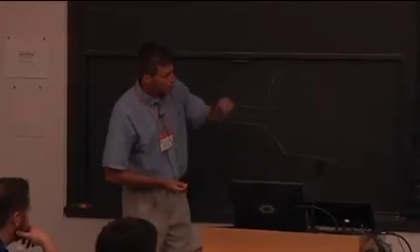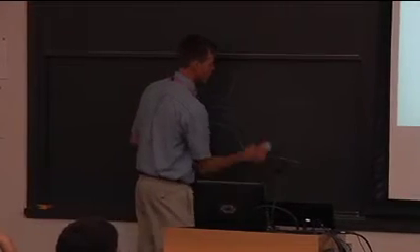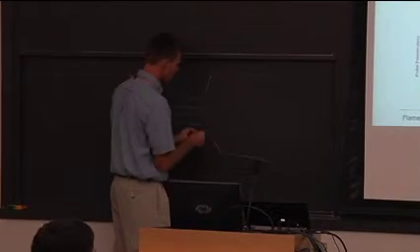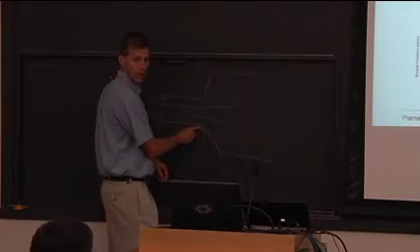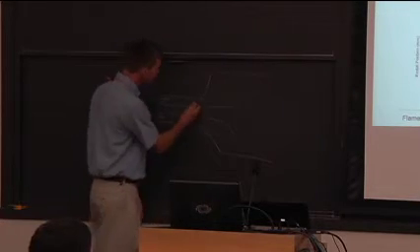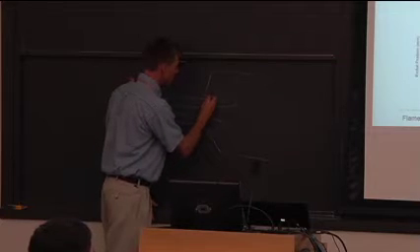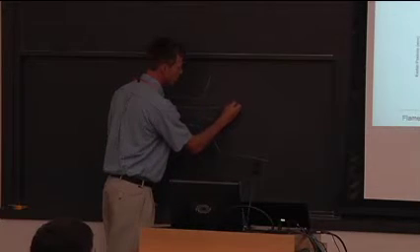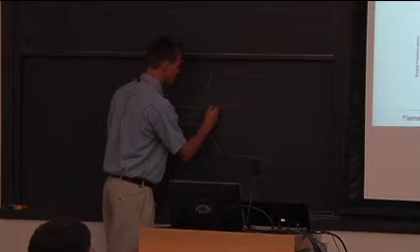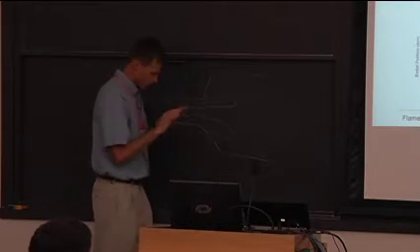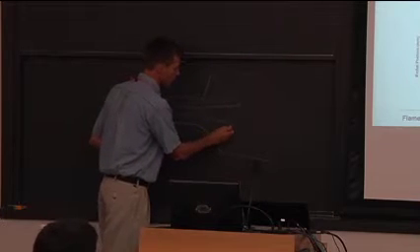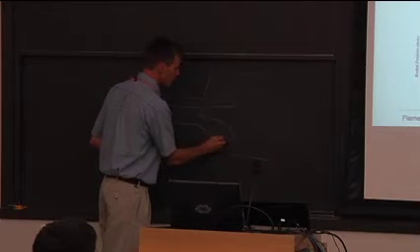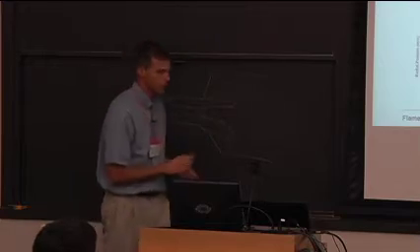What happens then, as you further increase the equivalence ratio, is all of a sudden, bang, the flame will wrap around and it'll catch in the outer shear layer. This is what I call the OSL. So now you have reactants, and this premixed flame is turning them into products as they propagate through the flame. So you have this annular type shape where the flame looks like this. And these discontinuities are very abrupt and they depend on lots of interesting stuff.